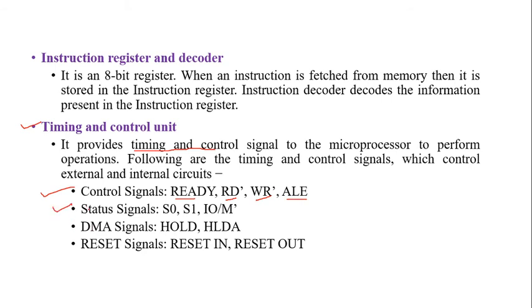Next one is the status signals, S0 and S1, which indicate whether it is an input output device or a memory location. Then after that, the DMA signals, that is HOLD and HLDA. And the last one is reset. Reset in and reset out are the 2 reset signals.